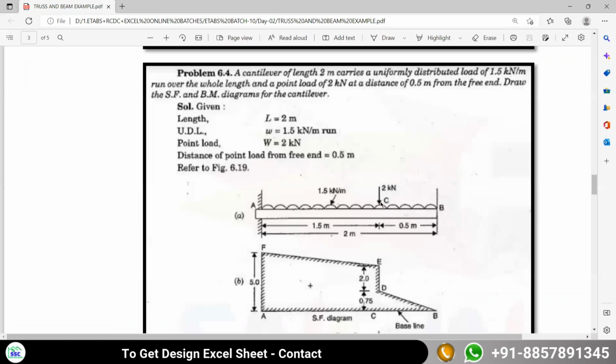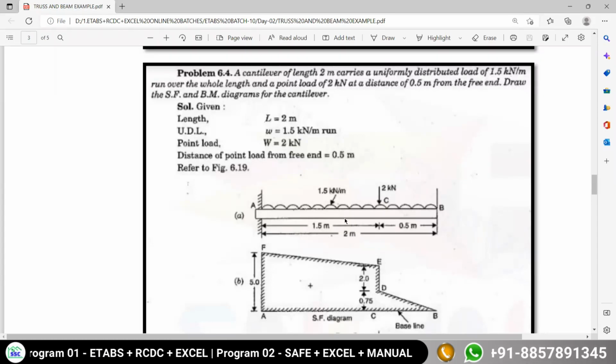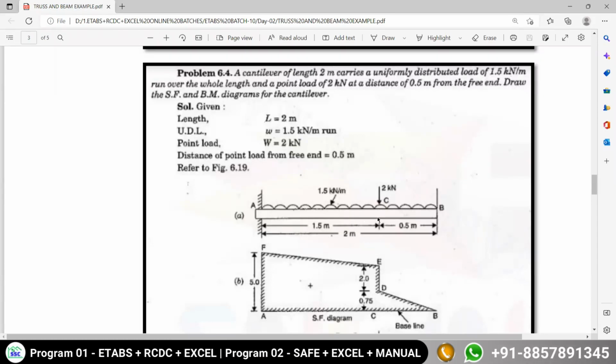And this point load you have to apply over the frame, over the beam. So tell me, it is needed to break the beam here, or I can take the continuous beam? No need to break the beam. Exactly, very good. In last session, we have covered this point. So it is not needed to break it. We can take a single element, it is a single beam. Okay, so why you are going to break it?